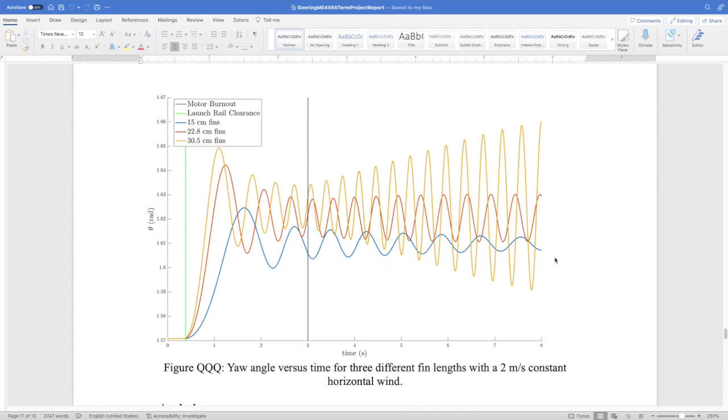they might get bigger. Also, it's just harder to be confident in the results of all these simulations for higher amplitude oscillations and higher angular velocities, because all these simulations assume that angular velocity is very small and angles of attack are very small. So that's probably not a great choice, and it does seem to be unstable, right? It seems like it'll grow forever, which isn't great.